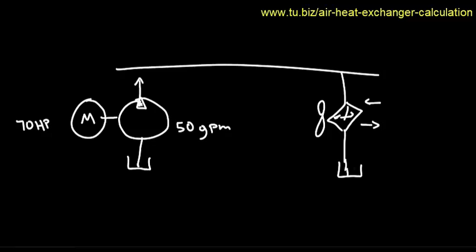So then you need to have your maximum system temperature and your maximum ambient temperature. What is the maximum ambient temperature that you have? Always go with the maximum ambient temperature. So in that case, you take into consideration the worst situation. So let's say ambient temperature is going to be 100 Fahrenheit.